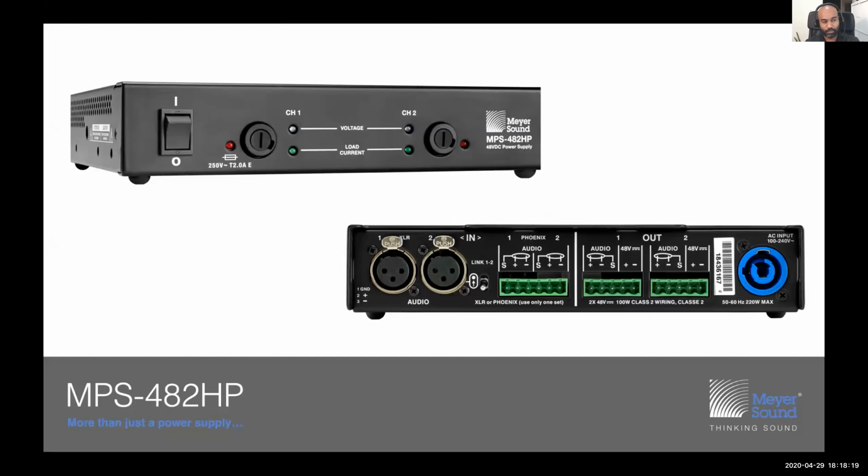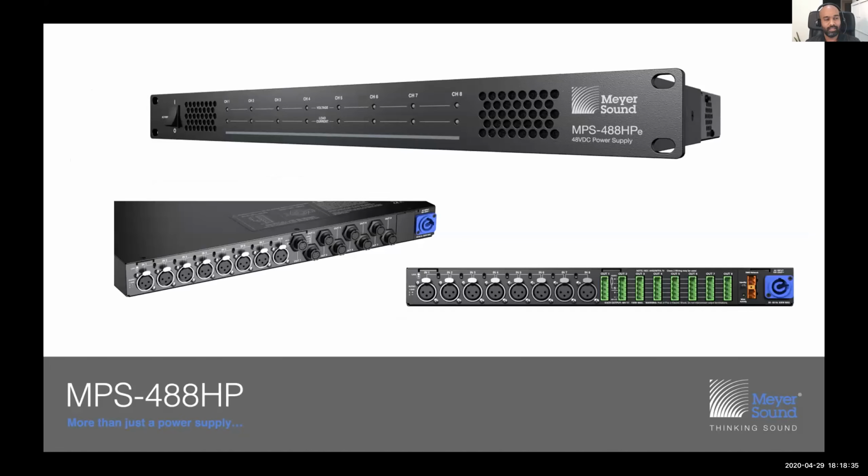Taking a closer look at the 482, in the front you will see LEDs. We'll talk about that. In the back we have 2 inputs, 2 outputs, or we can even link, making it a 1 in, 2 out, which is a nice option to have for distributed systems. Looking at the MPS 488, we have the same LED panel again, but now we have 2 different kinds of connectors. We have the EN3, which is a more secure connector. And we have the Phoenix, which is easily field terminated. You can easily terminate this connector in the field, so you can choose whichever you prefer for your project.